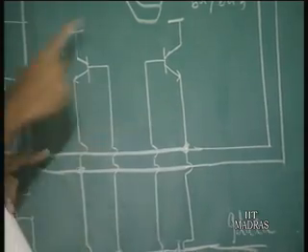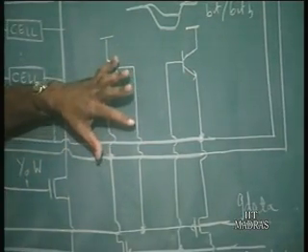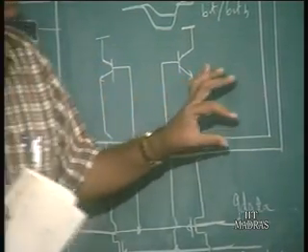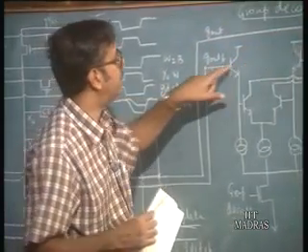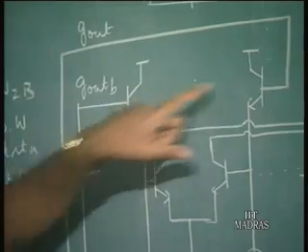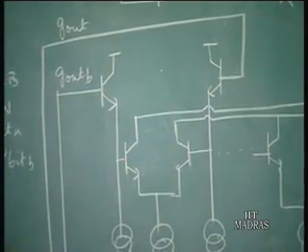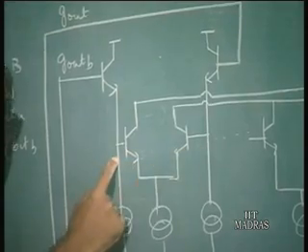This is basically used for writing operation. Okay, this part of the circuit. So, this 90 millivolt differential voltage is available here, at this point now. Now, these are nothing but emitter followers, and then this goes to the input of a differential amplifier.